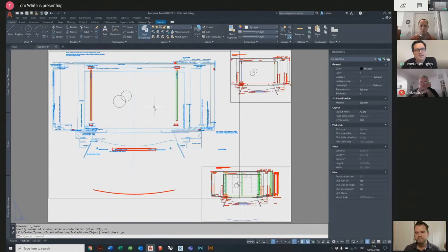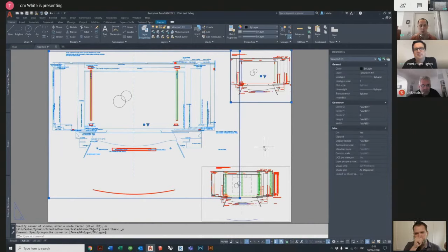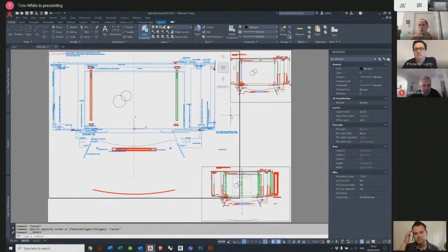I think paper space is so versatile and you can get your message across so easily. The biggest takeaway I'd give anybody is lock your viewports, because you can get into so much trouble so quickly without locking them. And as Tom showed, it's a very easy click of a button. So how do you lock the viewport? Either you can select multiple viewports. Oh, you can see that I didn't lock that viewport. So I'm going to select this one viewport without it being live. I can click the padlock on and off, or I can double click within a viewport and click the padlock on and off.